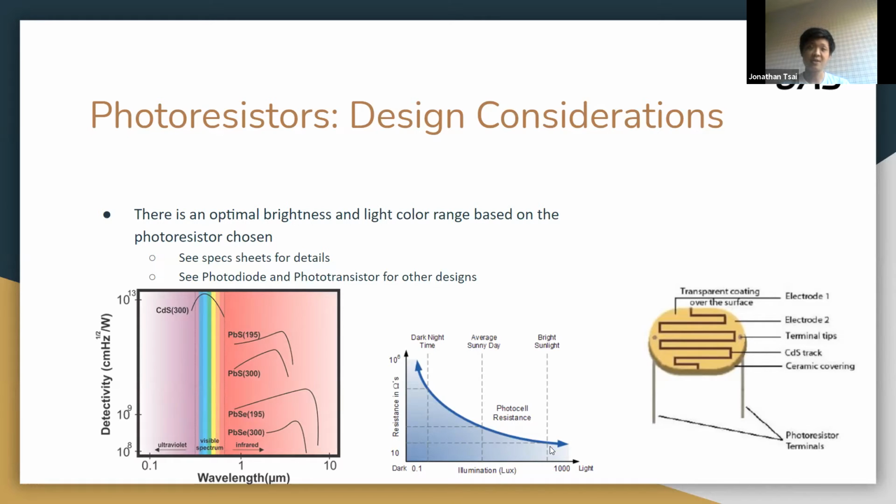So what this entails is you won't be able to tell the difference between something that's bright and super bright, right? Because you can't tell the difference between the two levels, your photoresistor is not going to help you out with measuring the brightness. Same thing goes with the dark end. While the resistance goes from moderately high to very high over this very narrow range, we just do not have the resolution to tell the difference between something that's dark and super dark.